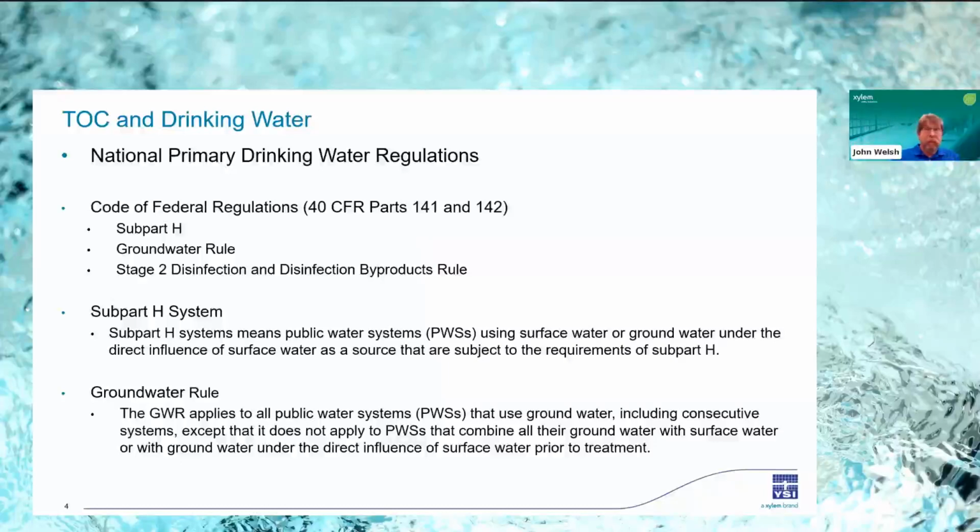Strictly speaking, TOC is not regulated in the sense of specific limits, say, for certain elements or other compounds. However, there are congressional acts and regulatory agencies that require TOC monitoring. These include the Safe Drinking Water Act, the National Pollution Discharge Elimination System, and the Resource Conservation and Recovery Act.